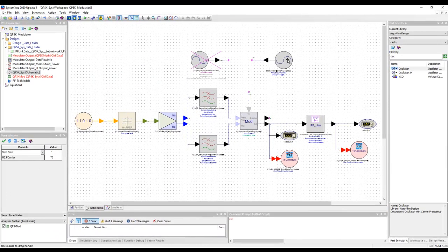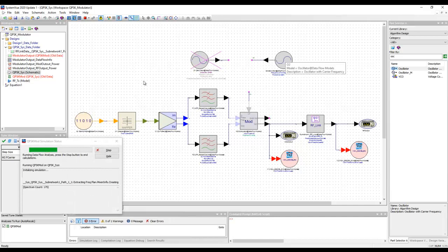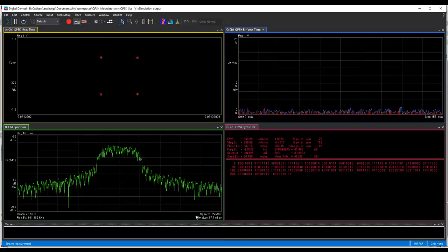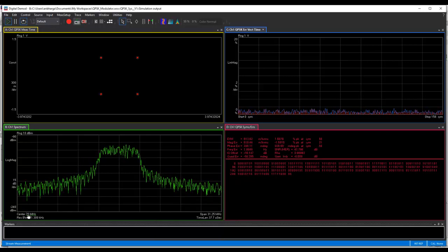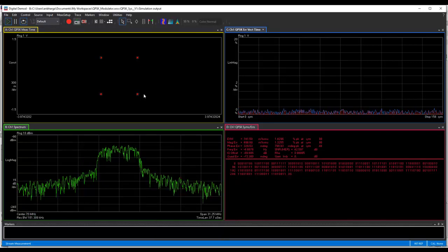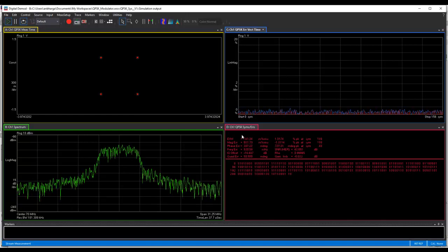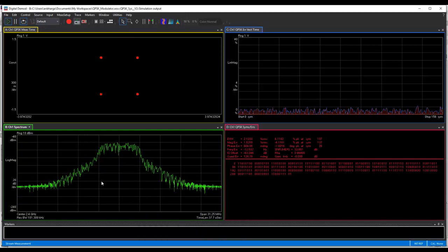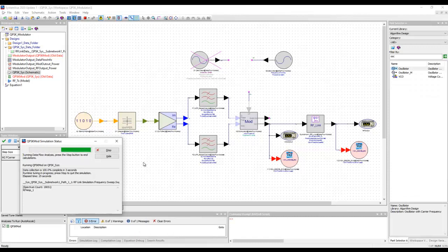However, when we run the simulation, I have activated no phase noise data in this local oscillator and we look at performance. So let's first look at the IF outputs at 70 megahertz. You can essentially see a clean signal without any phase noise effect. And we look at the RF output. Again, this is just the regular RF distortion where you can notice from the constellation there is no major impact, and then you have EVM around 2%, which is what we would expect.